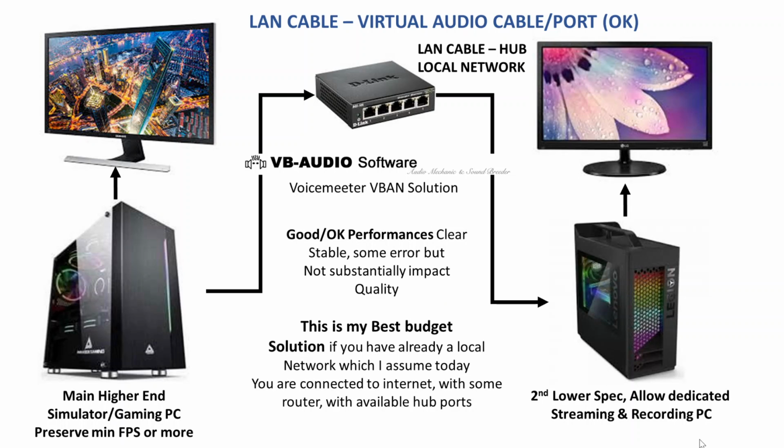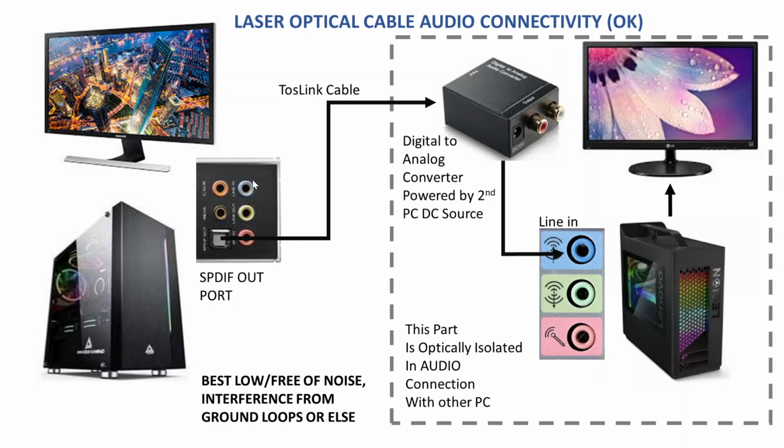because I've set this up as a backup to the main connection. This still probably uses some CPU power, because VB Audio definitely has to stream it from this PC to the other using the Voicemeeter engine, of course. So if you want to eliminate everything and use hardware only, the solution that I found best is using what we call S/PDIF, right? S/PDIF is this